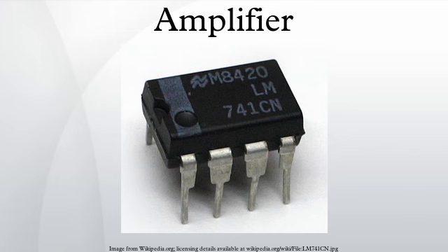Also, the use of fixed diode bias as shown here can cause problems if the diodes are not both electrically and thermally matched to the output transistor. If the output transistors turn on too much, they can easily overheat and destroy themselves, as the full current from the power supply is not limited at this stage. A common solution to help stabilize the output devices is to include some emitter resistors, typically an ohm or so.